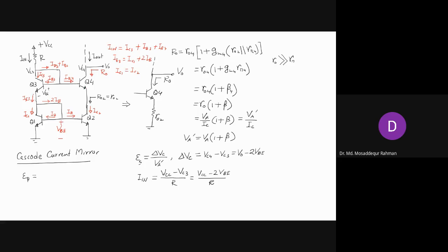Now here you see that voltage here is VBE, and voltage at this point is 2 VBE, right? And then you have another drop here, and you get also voltage VBE, right? So at both these collectors, voltage is VBE, same voltage. Del VC is 0 here, so you don't have that error, the difference in current due to output, because the voltage is same. So IC1 will be IC2, right?